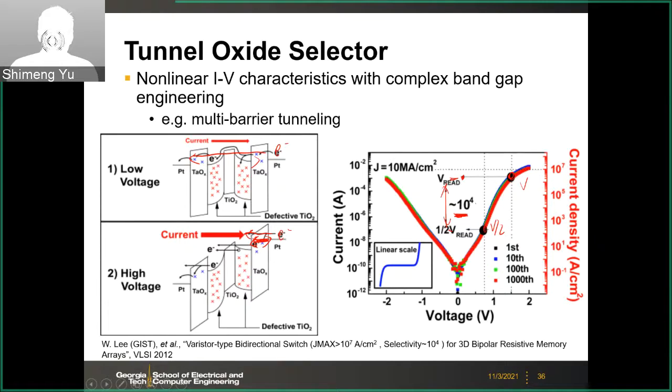And also we care about the current density at the on state, so how much current you can pass given the unit area. Here, if your area is 1 centimeter square, you need to pass like 1 megaamp, this is 10 to the power 6.